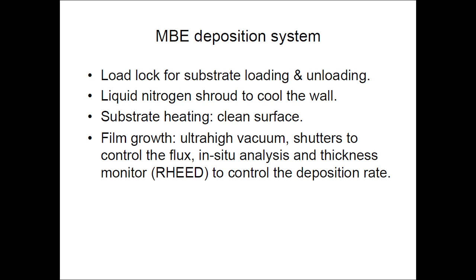What does load lock mean? Without breaking vacuum you can load your substrate and you can take back the substrate. Okay, without opening the chamber, without breaking the vacuum inside the chamber, one can do that. That is what the load lock is for, substrate loading and unloading. And liquid nitrogen will be used to cool the wall because a lot of heat will be produced. The substrate heating also will be managed by providing liquid nitrogen. Okay, the substrate heating will also clean the surface.